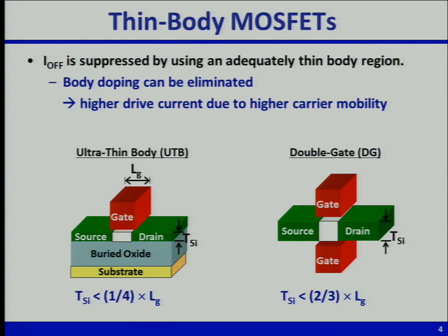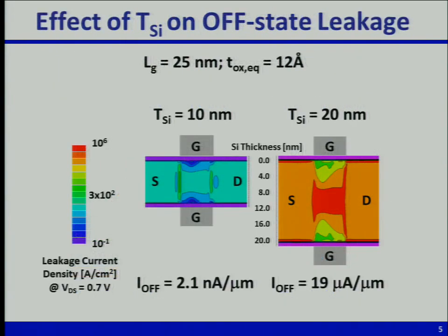Now it turns out that in order for the double gate transistor to work well, the front and the back gates have to be perfectly aligned to each other, and they should be self-aligned to the source and drain to minimize capacitance and parasitic resistance. And you need high performance. If you want high performance, this has to be a single crystalline silicon channel. So it's very difficult to form and pattern a gate electrode underneath the channel, then form a single crystalline silicon channel over it, and then another gate electrode on top that's perfectly aligned. So basically a challenge.